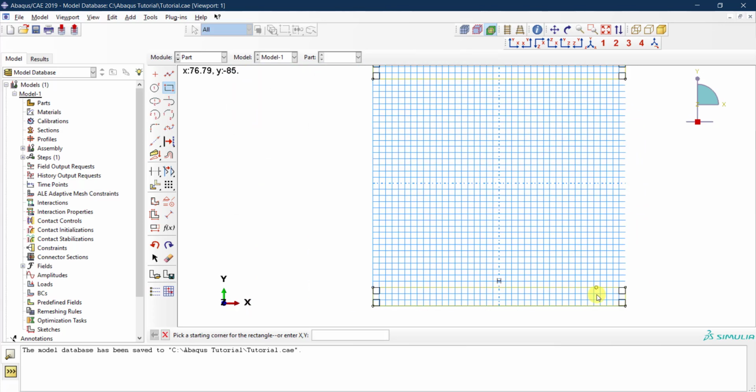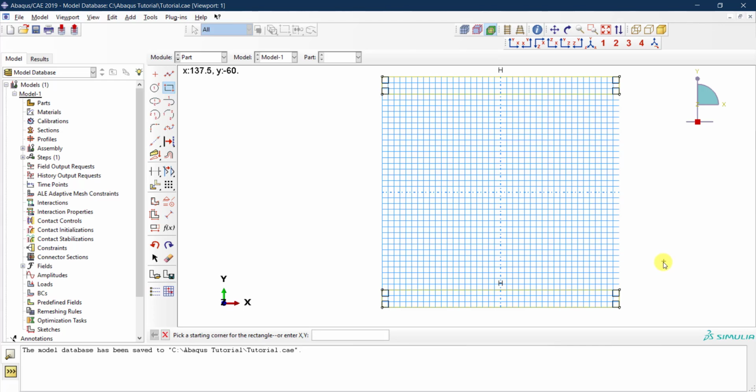So this means that if I want to modify something, let's say I modify this length, which is something we're going to see in a second. If you modify this length, then the length of this side will increase, for instance, if you make it larger. And at the same time, because you have all these constraints that this line needs to stay horizontal and the angles need to stay at 90 degrees, the opposite side will also increase by the same amount.